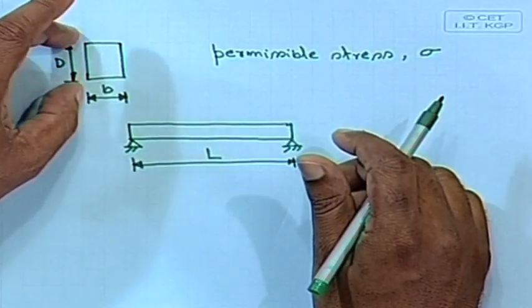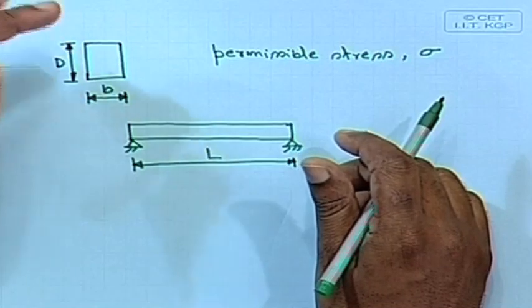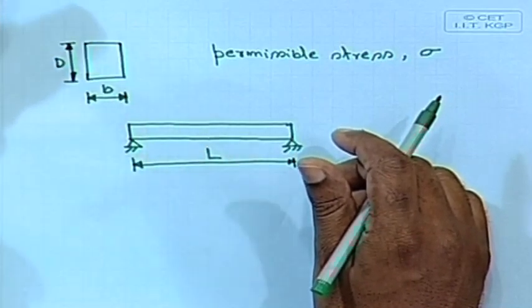The beam has two parts, one is the bending moment, which is the governing one, and the other is shear force. For the time being we are considering only bending, that means we shall check and resist bending only. Whatever section we provide will resist the bending coming due to the external load as well as the self weight. So, we would like to provide a simple section, say a rectangular, homogeneous section, maybe made of steel, aluminum, or wood.